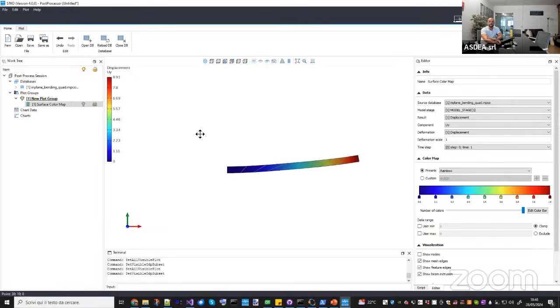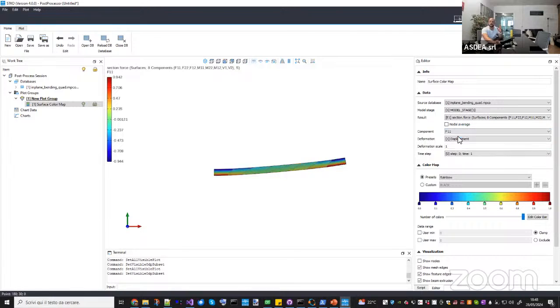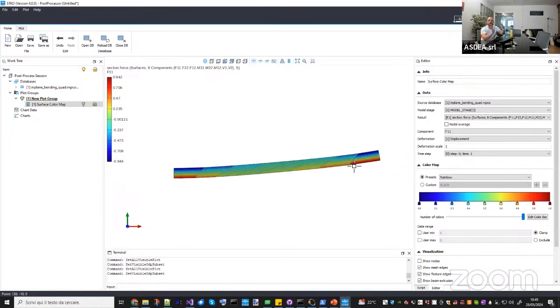So now you have a displacement which is 1/2 of the expected solution, and the same thing happens. So instead of being 20, it is 9, more or less, so slightly less than 1/2. And if you look at the forces, also here, you don't have a force which is equal to 1. Once again, it happens the more the element is distorted in the angular direction.